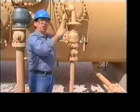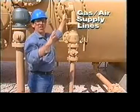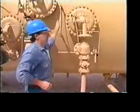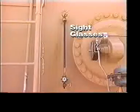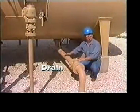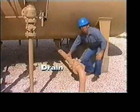Connected to the level controllers are gas air supply lines. These lines supply either gas or compressed air to the level controllers so they can work properly. These are the sight glasses. They help the operator see the water-oil interface levels in the treater. Now, on the bottom of the treater are drains for emptying the vessel for repairs or to remove accumulated solids.